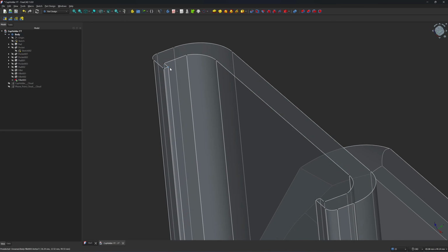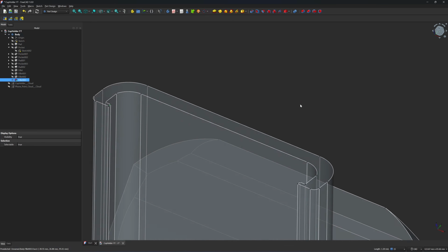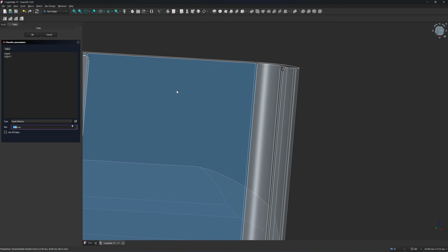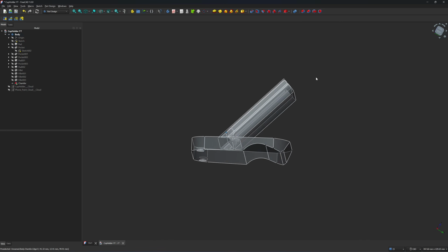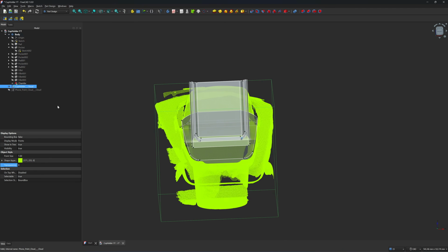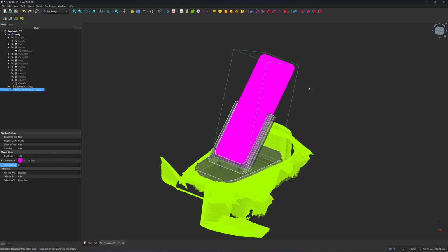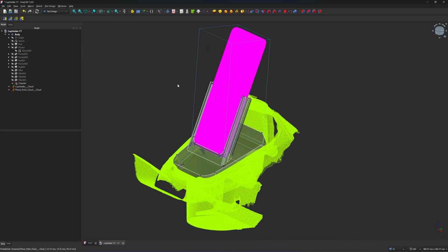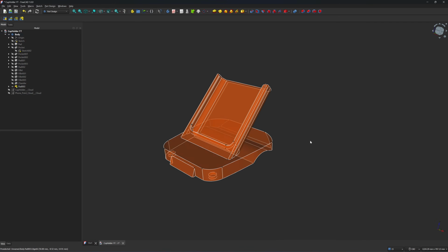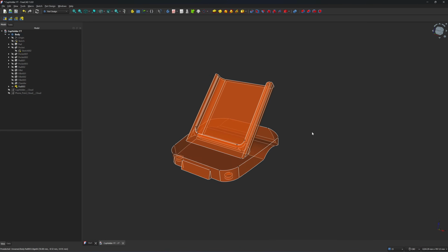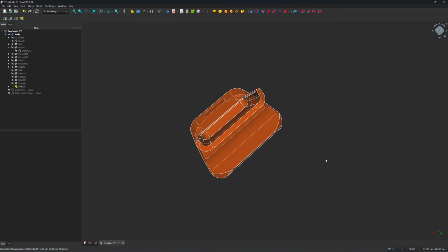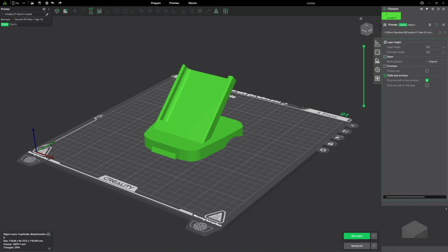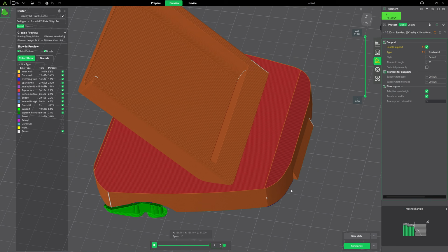We have a sharp edge here. I'm gonna chamfer it. This edge and this edge chamfer. 1 millimeters. Let's say 2. Okay, 2 millimeters. Click on OK. Looks like we have finished our phone holder project. Okay, the point cloud of the phone is too dense, I can tell you. Let's export this one. Okay, let's try to print with support enabled.